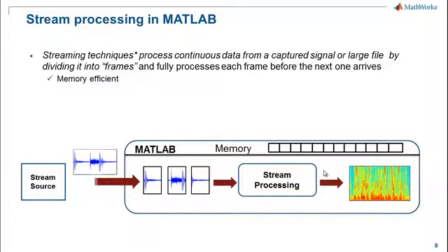When you are working with large data sets or continuous live data where all of the data is not available at once, you need to process the data in few samples or blocks of data called frames one at a time. Streaming techniques process the continuous data by dividing it into frames and fully process each frame before the next one arrives. A key benefit is memory efficiency, which results in a smaller memory footprint.